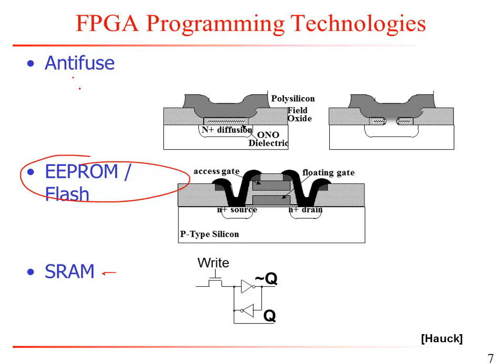And then you have Actel, which makes anti-fuse programmability. So anti-fuse programmability basically uses some fuses or anti-fuses where you apply high currents or high voltages on something, and then you permanently make a connection or disconnect a connection.